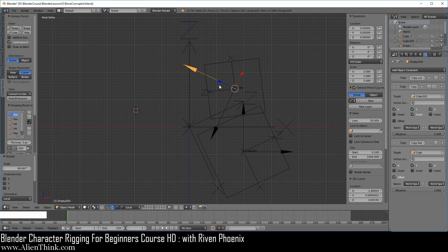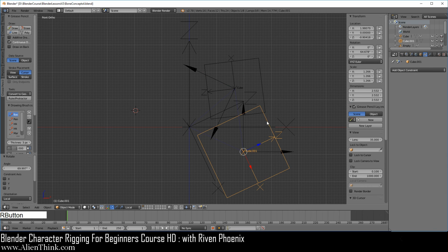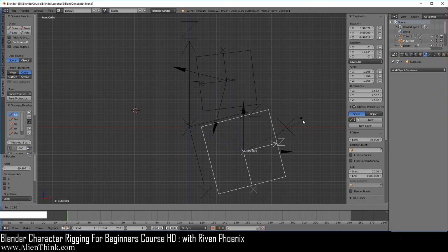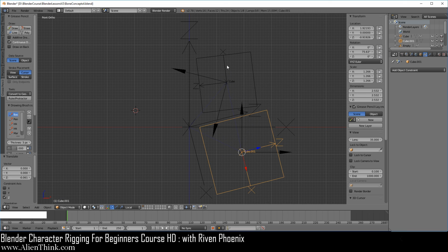And that's it. Now remember, you have to keep this on invert because we're still looking at this object in local space. So when we press the R key to rotate, you'll see how this works. Okay, so this again is a local, right? Local means that this z-axis becomes its local coordinate system. So when we click on z over here, this is going to move along this global z.